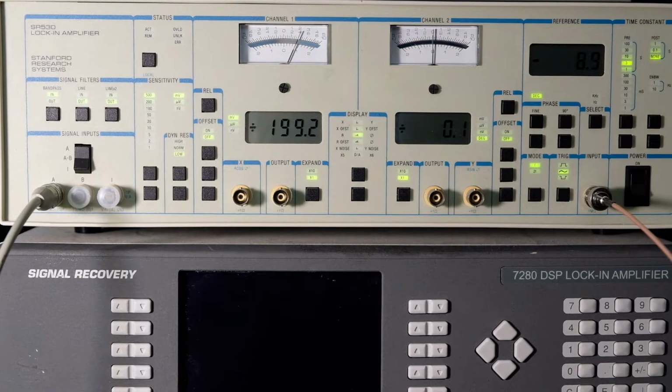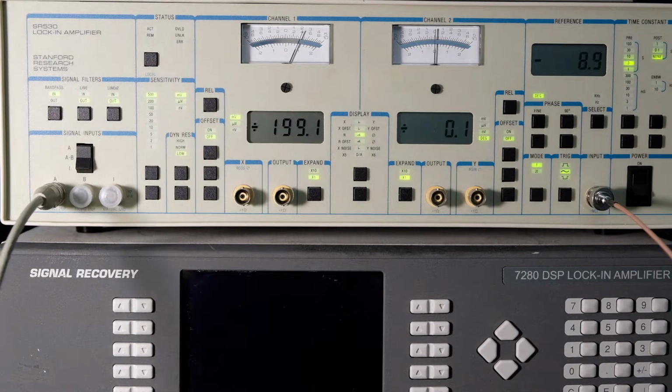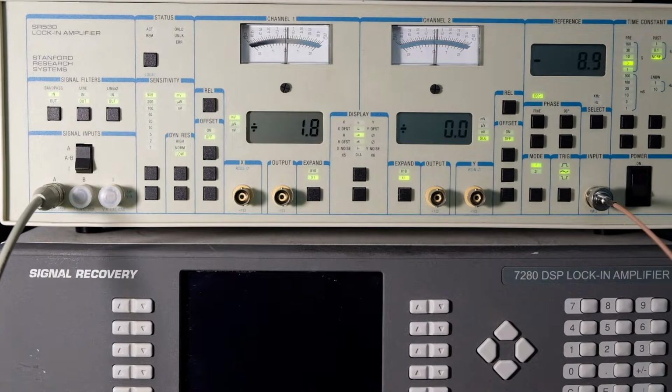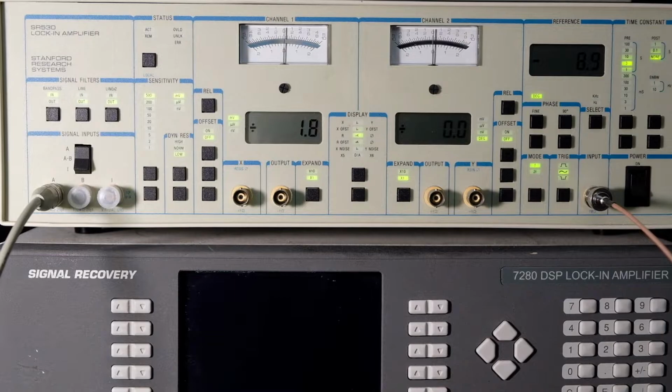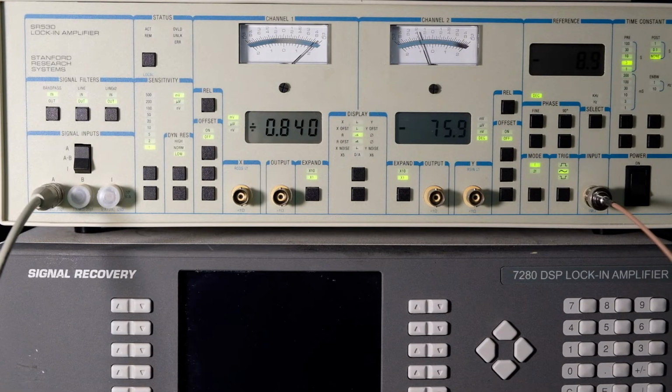So now I can connect the capacitor and see what we get. I'm going to be connecting the capacitor just across this terminal coming out of here, across these two, and the voltage will of course drop because the capacitance will effectively short this source. The source impedance is 50 ohms, so this will drop to microvolts, millivolts, whatever. We'll see what happens. Okay, almost there. So it's now connected, the capacitor is connected, and of course I'll reduce the scale here. So this is the 1 millivolt scale right now.